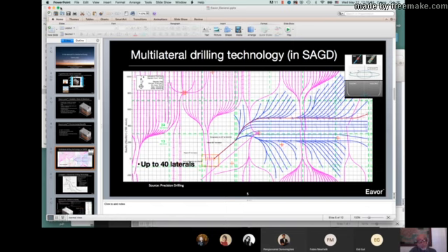Just to make a comparison, now a 5 megawatts geothermal power plant made with a binary technology, you need to build something like 17 wells, say 15 in the end. 15 wells at a cost, say about 2 kilometers deep, and at a cost of €1 million per kilometer. So each well will cost by itself about 2-3 million euros.